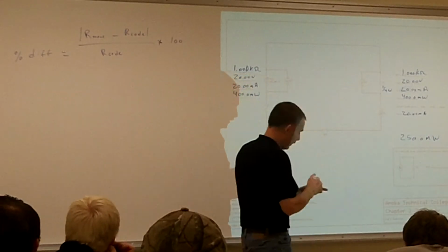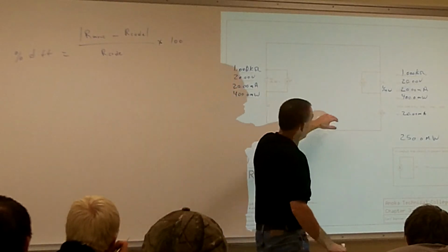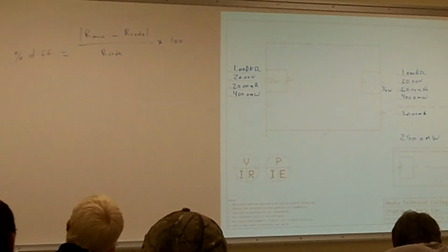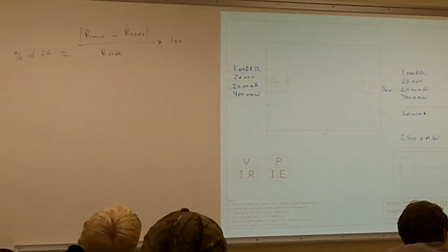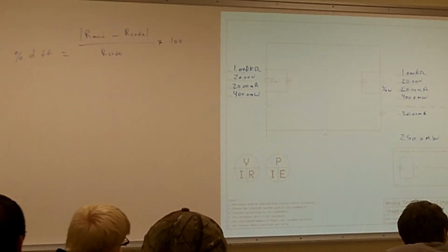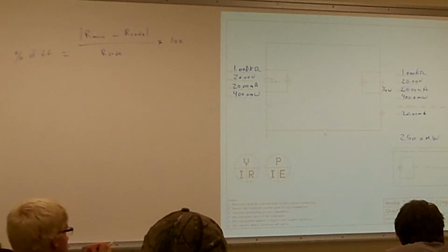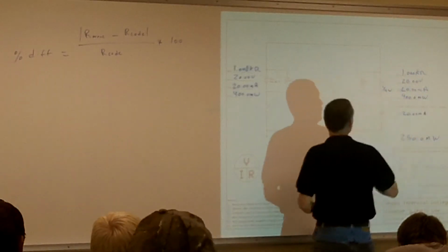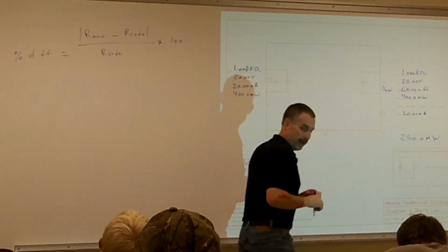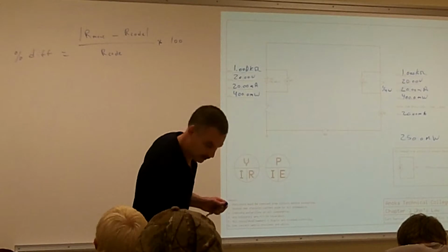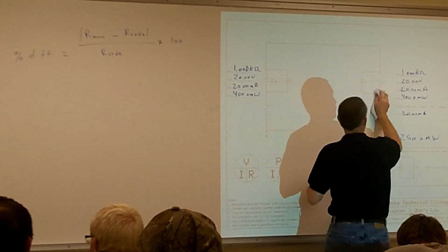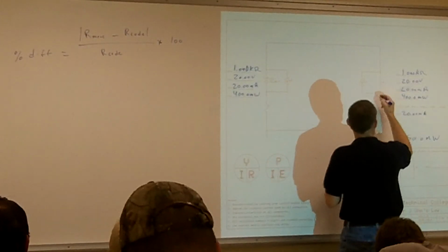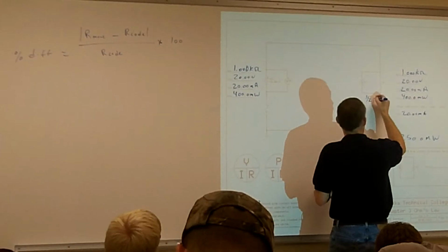So we have to make sure that we size up our resistors accordingly. Remember when I handed it out, this resistor can have the same value as this resistor. This one just can handle more heat. It's got more surface area, and it can dissipate that heat a lot more. So we have to be careful about that. We have to make sure we size our resistor to the right thing. So we have to jump up to what size wattage resistor? Half watt. It goes from 1/8, quarter, half, 1, 2, 5. So you want to make sure that this thing was a half a watt.